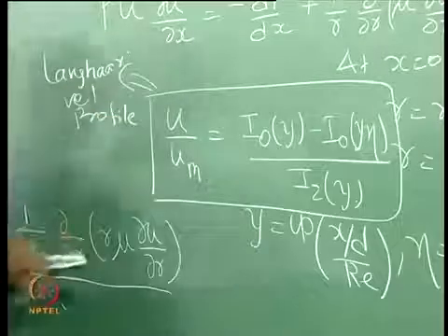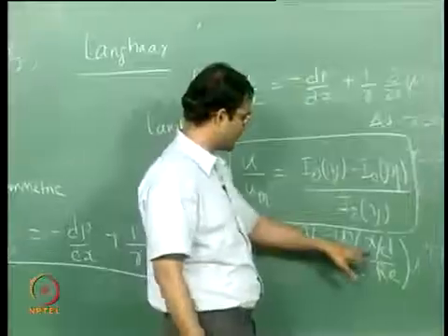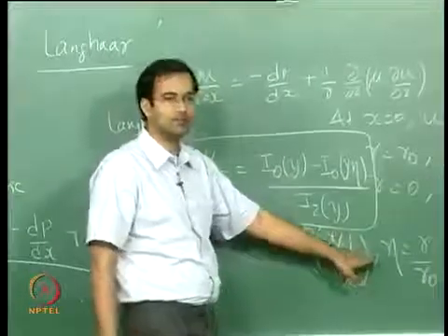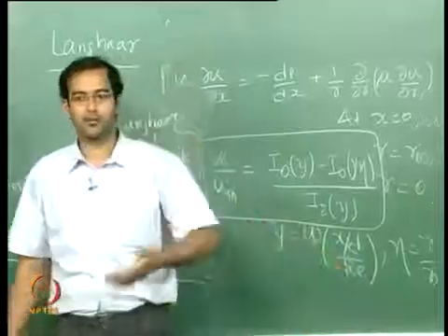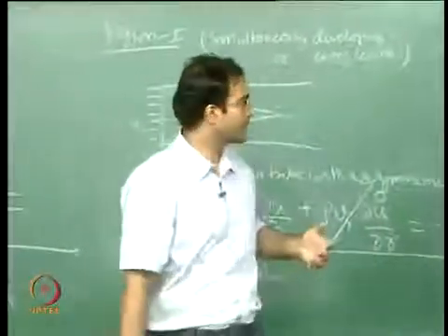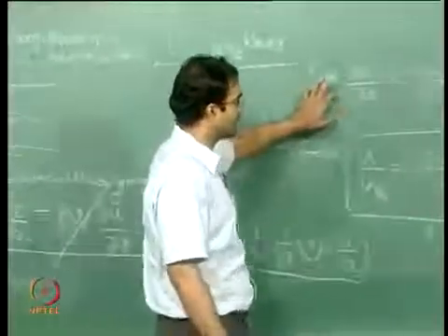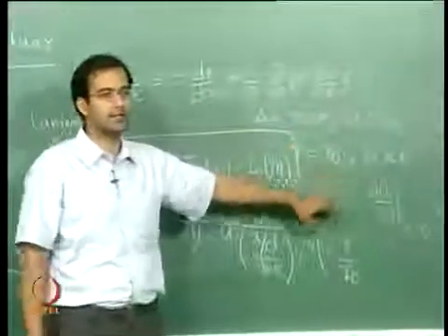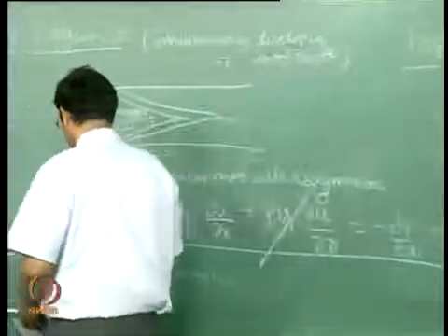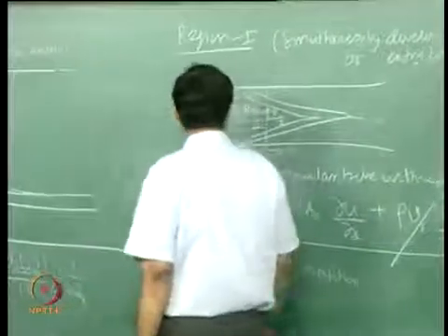So you see now the velocity profile is a function of x by d through the gamma, as well as a function of eta. Okay, so this is the approximate profile that Langer got by the numerical solution to this equation with the following boundary conditions. Of course he neglected a lot of things here, so he neglected the radial velocity and things like that.